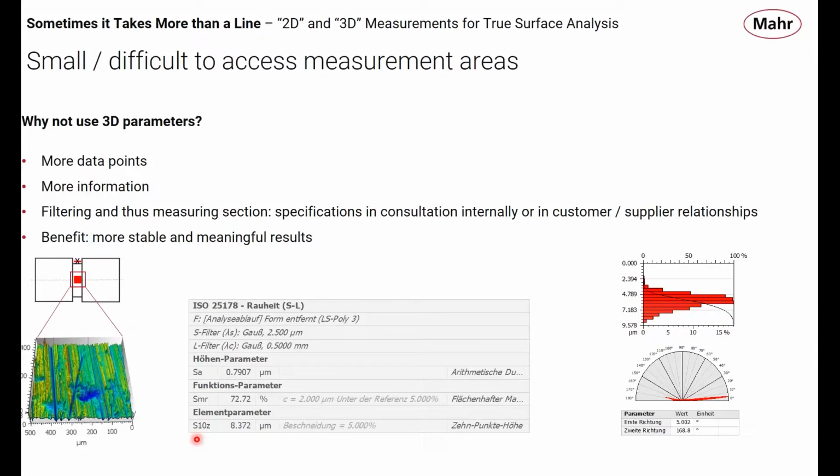We have 2 orders of magnitude more information than that from a single measurement. My proposal is that that is going to give you a much more reliable representation of what's happening in that groove than a 2D measurement. And here we're showing a typical 3D measurement that we would use, producing the Sa value, which is the 3D equivalent of the Ra measurement.